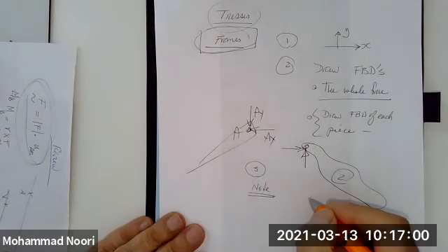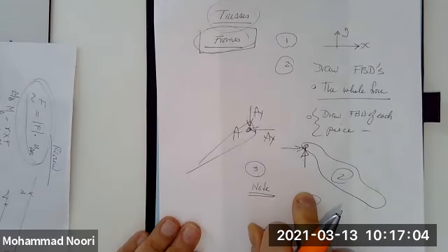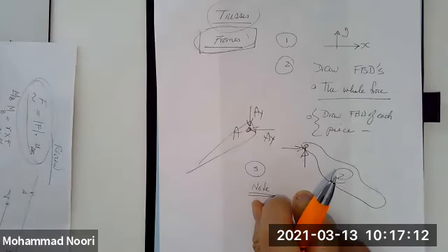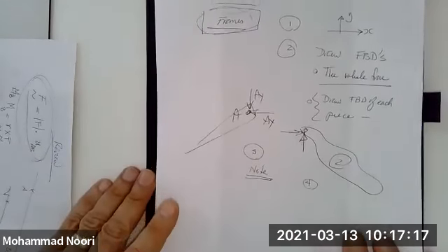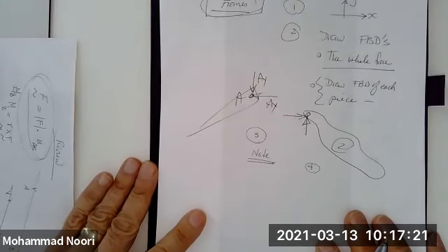All right? So you start with the member with the least number of unknowns. Try to solve for as many unknowns as you can. Move to the next free body diagram with the least number of unknowns until you're done. And what happens at the end? What do you end up with? Anybody? You end up with something extra. End up with what? A free body diagram.